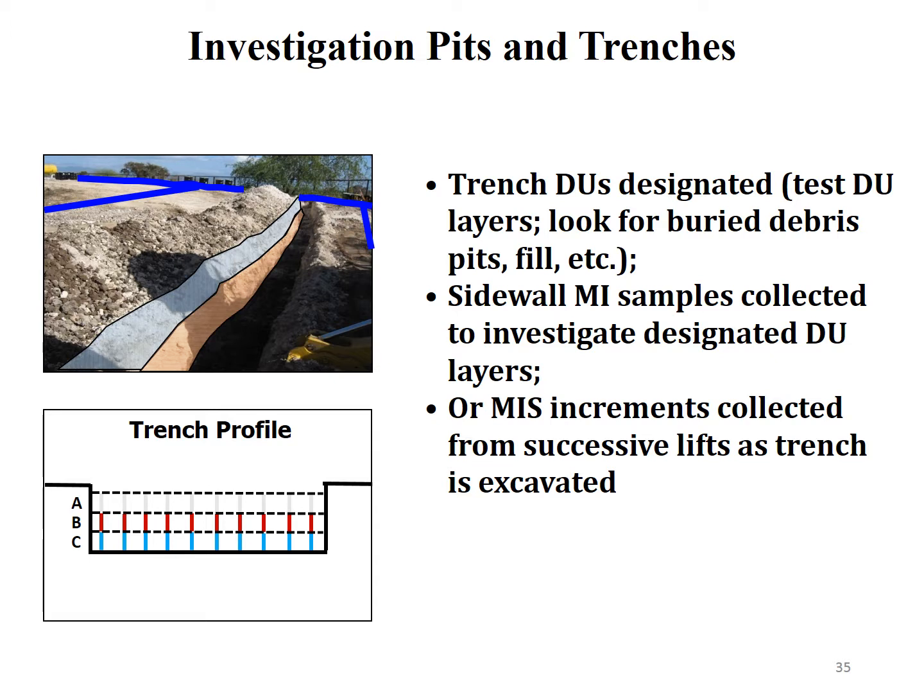Pits and trenches can be approached with the use of mechanical equipment, and that could be an efficient option if the site is open and the mechanical equipment is available. Once the trench is open, we're typically sampling one or more vertical increments up the sidewall of each depth interval in as near a core shape sample as we can.